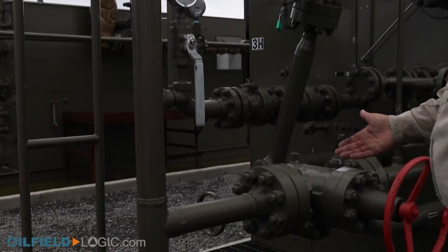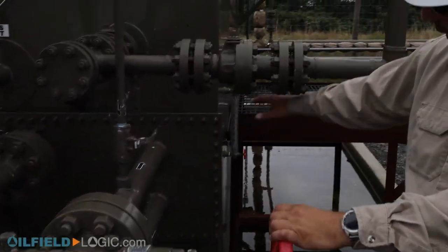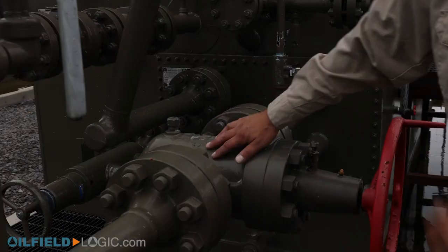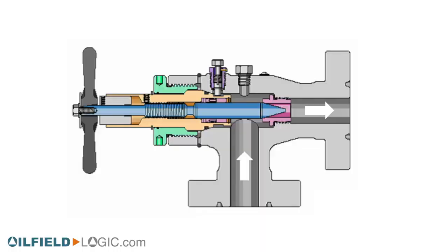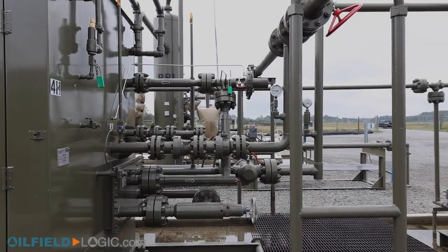Inside that bath, you can see by the flow, we're going into this indirect water bath. There's coils that run in and out of this, surrounded by that warm glycol, 100 degrees, choking the pressure and flow with what we call a manual choke. Some units have an automatic choke that we're starting to implement on some of our newer designs, where we can adjust that through an app on our phone or through SCADA off of our laptop.